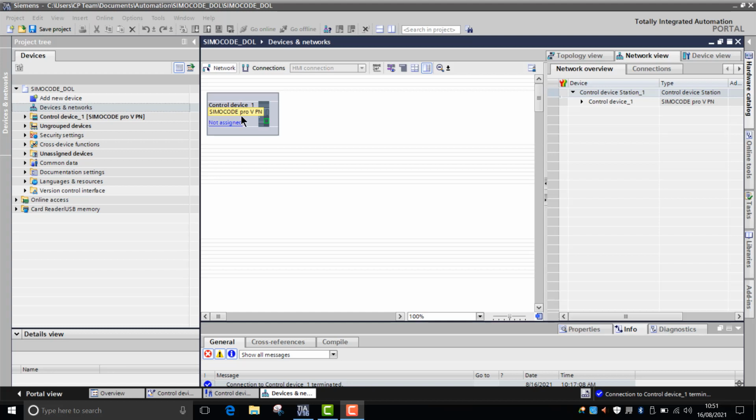So why would we use this undervoltage function? Typically, if you have a dip in voltage, it causes a higher current for a constant power supply. The higher the current, the more heat it creates, and that could damage the motor. So if you're utilizing some form of monitoring on the undervoltage conditions, you'll prevent the motor from any damage created by any undervoltage that the system might see.